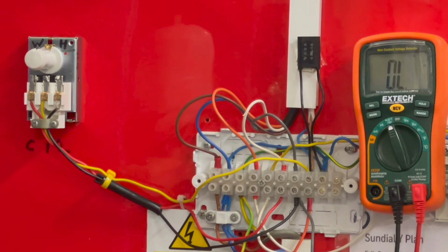If we were to do it in mains live, then we would simply go to an earth connection to common, and then to 1 and 2, and that will tell us where the diverter valve is and the cylinder stat is. And that would be terminals 6, 7 and 8. They're the 3 terminals where C, 1, 2 go to. And that concludes testing of a cylinder thermostat.